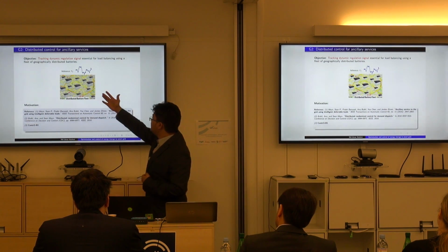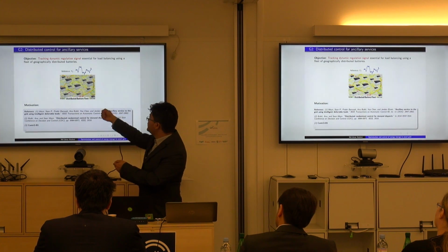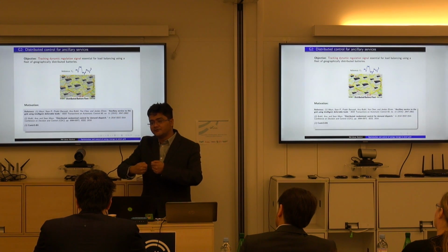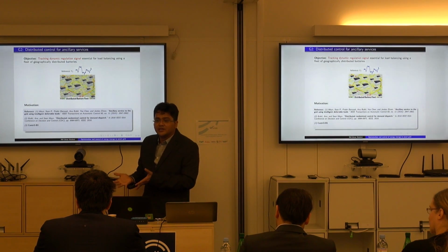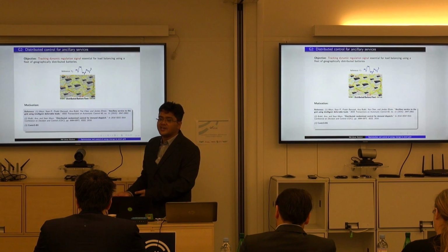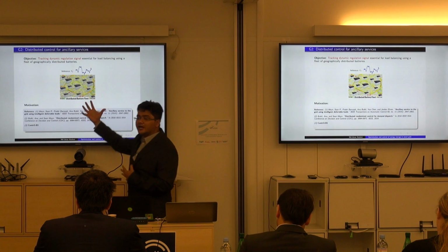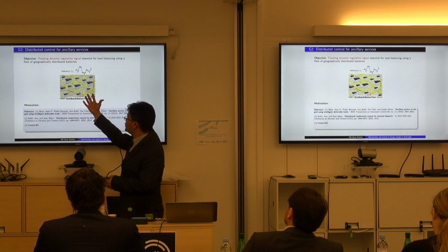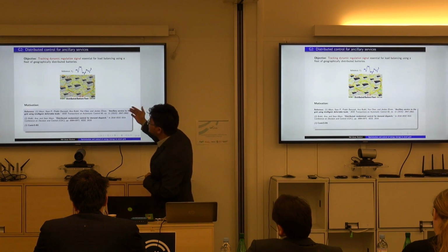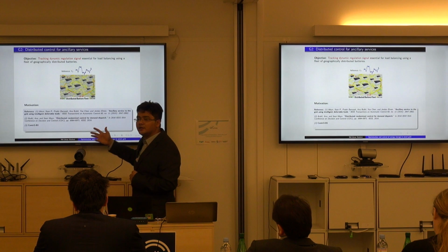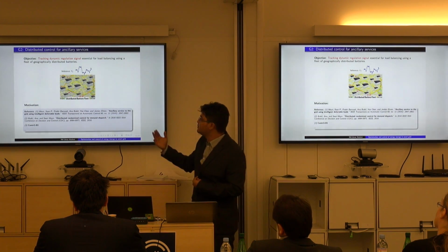For example, some of the balancing authorities generate a regulation signal, and this regulation signal indicates their needs, whether someone should increase consumption because there is too much power in the network, or decrease consumption because there is scarcity of power. So suppose fast ramping resources are spread in a geographical space. Now how do we control this large number of batteries? This is an extension of my supervisor's work on load control, distributed load control applicable to batteries.